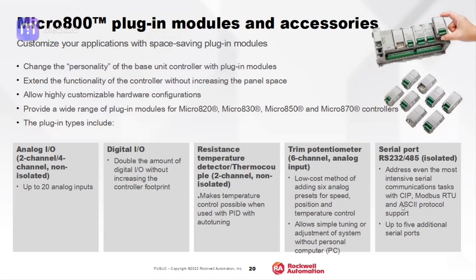If you want to add more serial communication, for example to exchange data between power meters and the controller, you can utilize the maximum plugins based on the base controller's plugin options. If the controller supports a maximum of 5 plugins, you can go with 5 serial modules.